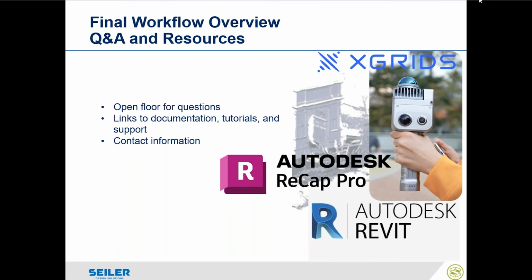Tim Johnson asks, what is the vertical accuracy? Because it's a LiDAR-based unit, it's not like it would be in photogrammetry where we have a ground sampling distance and a plus or minus vertical accuracy. It's a 3D LiDAR scanning. So local accuracies are going to be in that 1.5 centimeter range of the scan head, so your vertical accuracy is going to be the same. It's a 3D overall accuracy. It's not a vertical accuracy.